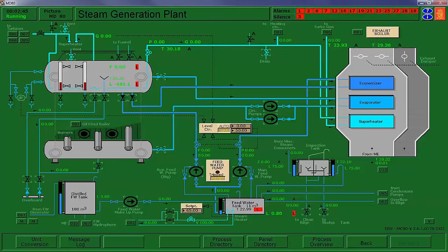and I'm going to start filling the feed water tank. This is too low, and we're going to fill that to above 1 meter. So we'll start that up. While I'm here too, I'm also going to open up the steam valve to the feed water tank. Again, we're lining up systems ready to go. So we want the small one, and you see down here, the upper one is the small.